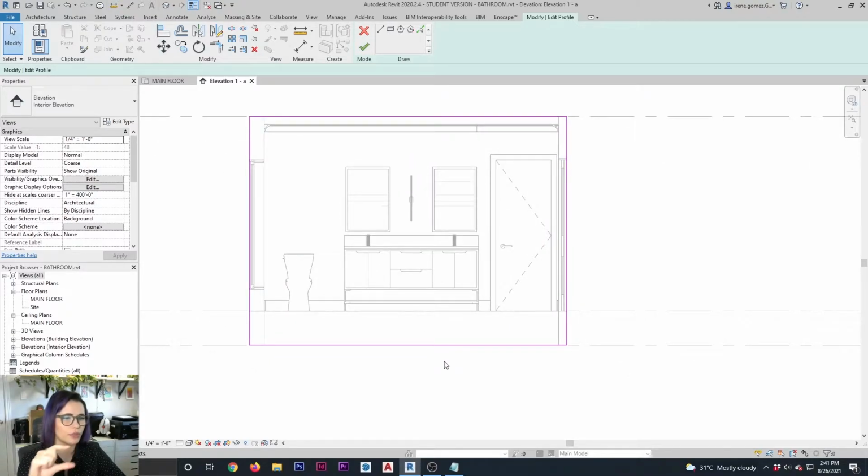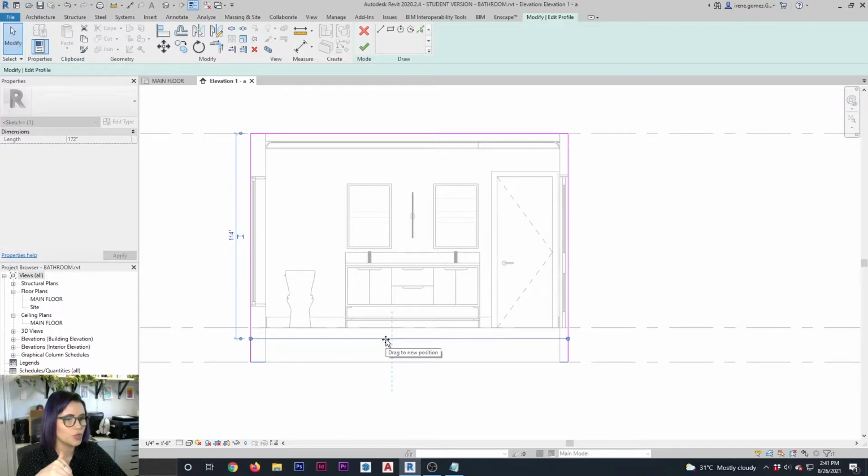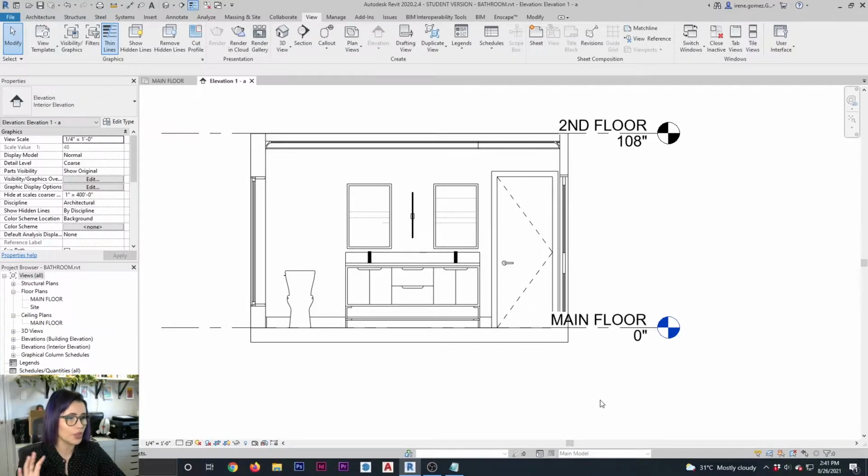And now with my floor, I'm actually going to reduce the thickness, because I don't really need to know the full thickness unless you're doing something really unique, like a double height slab or something like that. You don't really need the full thickness of your floor. So I'm just going to drop it here, so it's more similar to what I have for my walls and ceiling. So that looks good, and when I click OK, now we can see the boundary box of this space. So that would be the first thing.